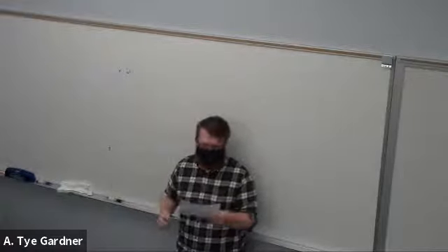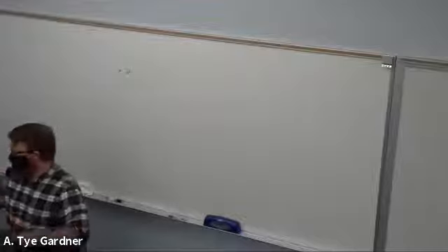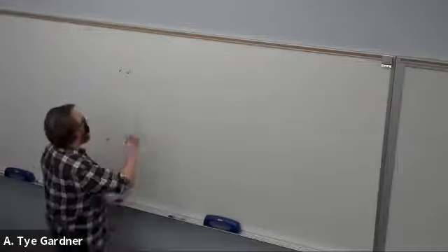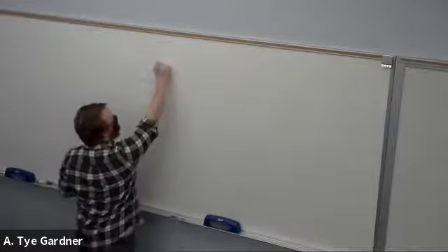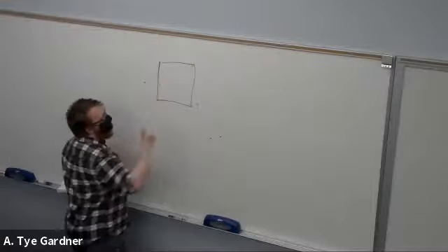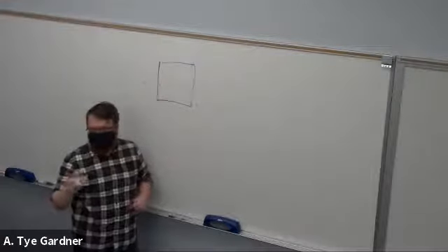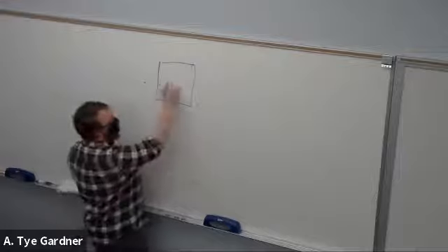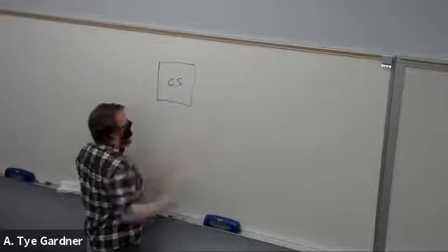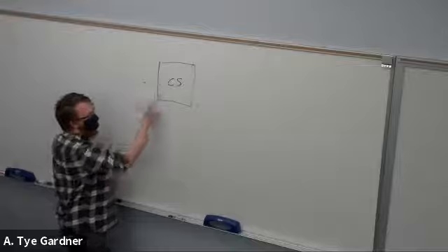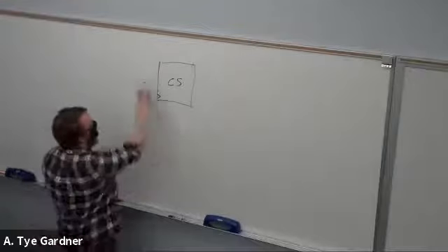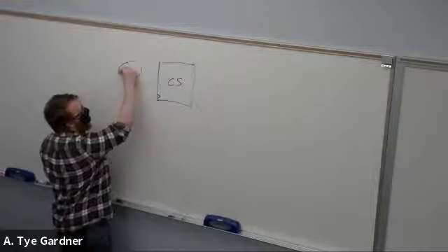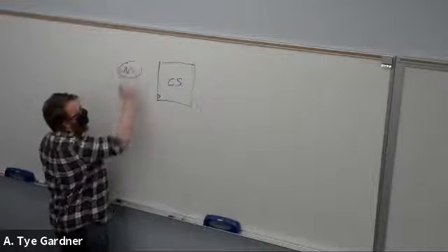All right. So, state machines. If you recall this figure, the first thing we need to do is remember where we are. What is our current state? This is just a register, right? It's clocked. Then we need some way of determining what our next state is, and we call this our next state decoder.